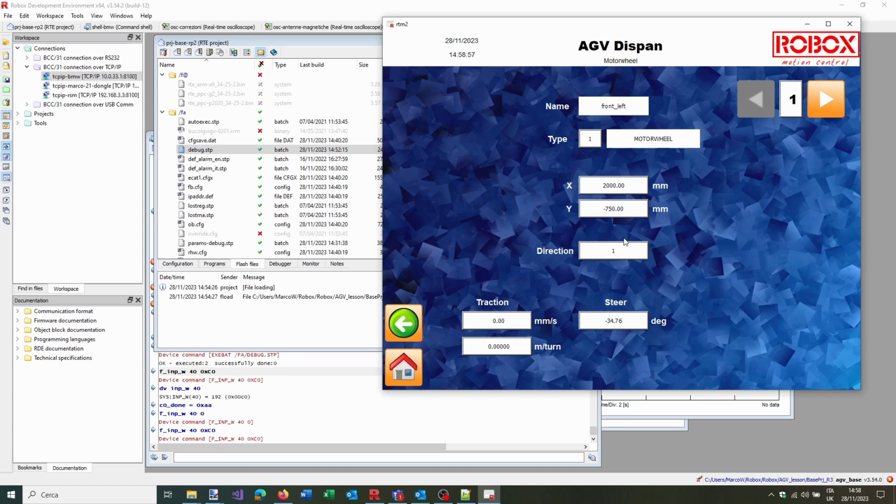If your drive is connected in the reverse mode, you can modify this bit just to make it move forward or backward. I suggest to you the first time you switch on your AGV, keep it lifted from the ground in order to be allowed to play manually and avoid it to escape from you. You are never sure your AGV will behave in a correct way, so please make yourself safe.